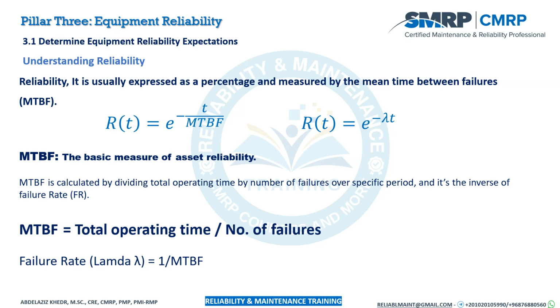For example, if you need to measure your reliability to operate for 90 hours, to have a pump running for 90 hours, for example, you will have T as 90 hours, then you will substitute for it here, 90 hours. If you have your mean time between failure as 1000 hours, you can calculate it through the calculator and you will identify what your reliability is exactly.